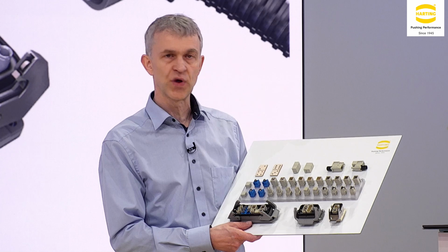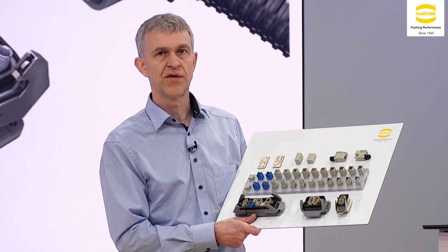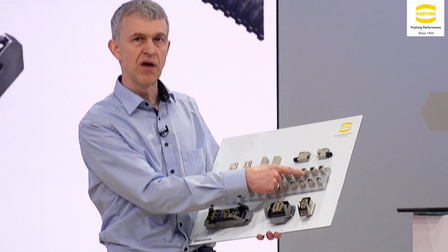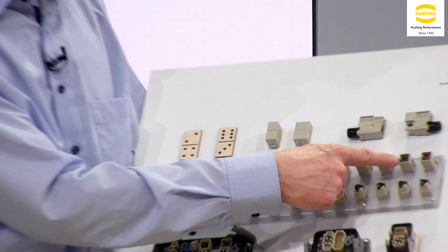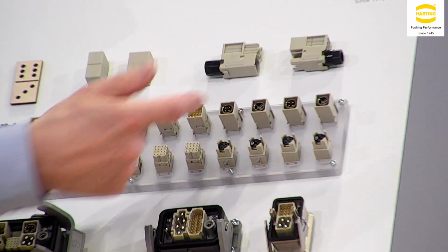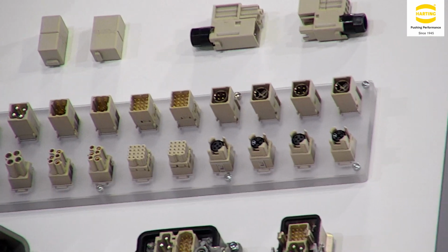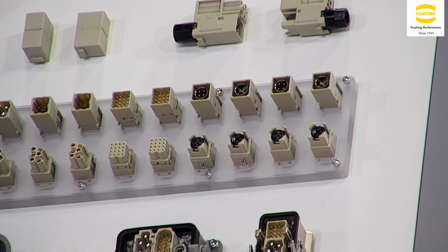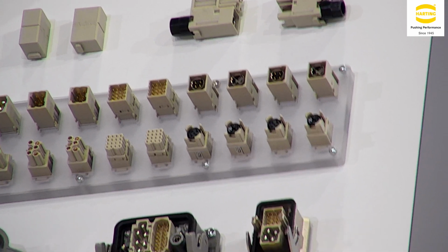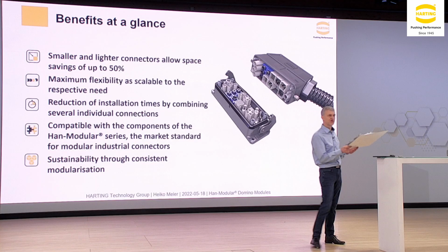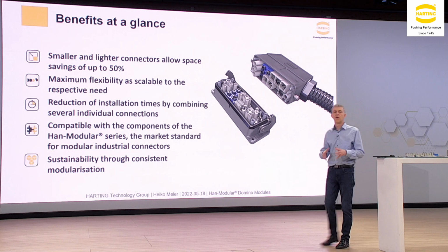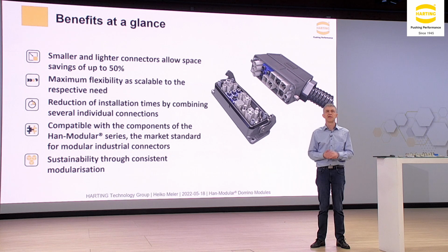We have several shielded solutions. If we look just at the Dominoes, we have here the M12 cubes. Those M12 cubes are shielded connectors, and in those modules we have 8 shielded contacts. So by this shielding, the isolation between other modules near a power module is given.